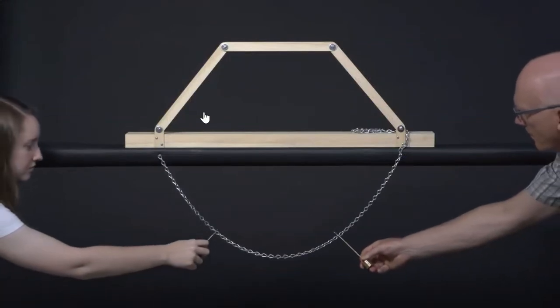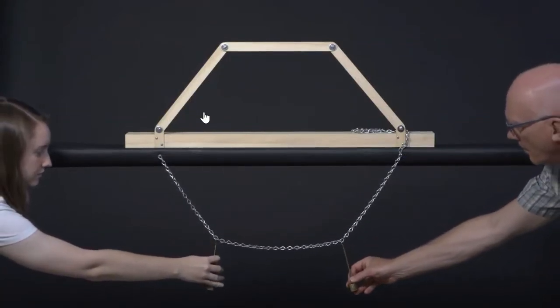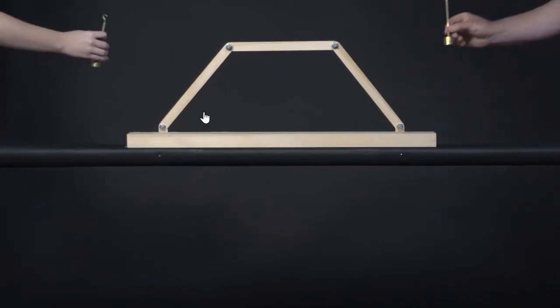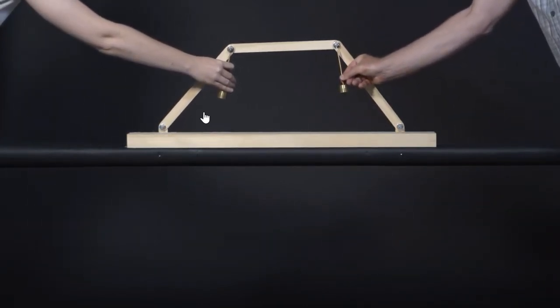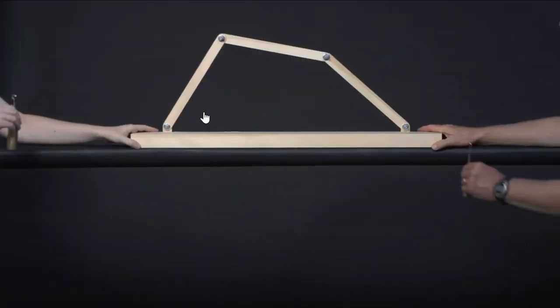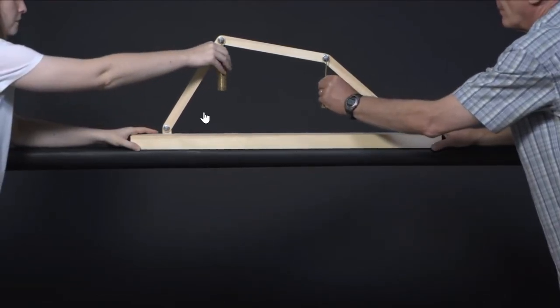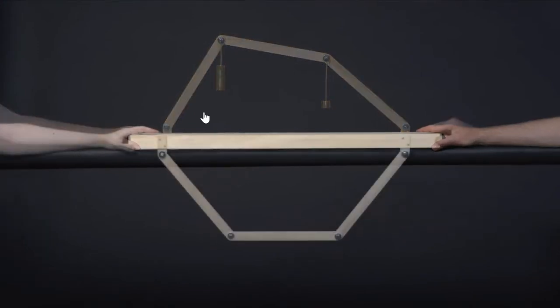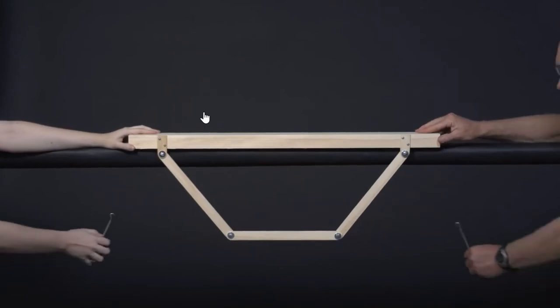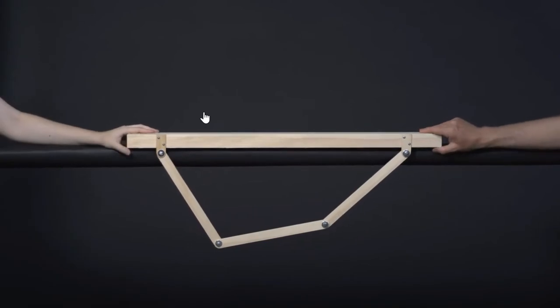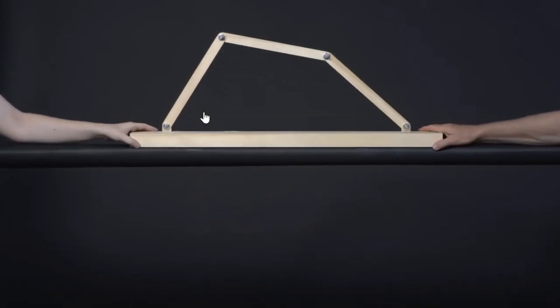Here is another difference between chains and arches. Because chains are tension systems, they automatically reshape to better carry whatever load is applied. Because arches are compression systems, they do the opposite. So if they are not shaped appropriately for the loads they are asked to carry, they can collapse. As a result, designers must tailor each arch to the loads that it will need to carry. And how did we figure out the shape for the arch? That was easy. We just hung it upside down so that it worked like a chain system, applied the loads, and maintained those angles when we turned it right side up.